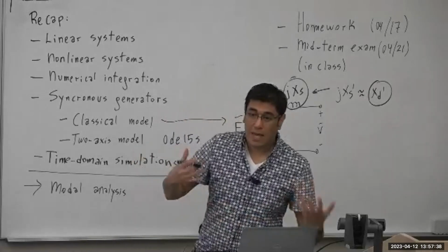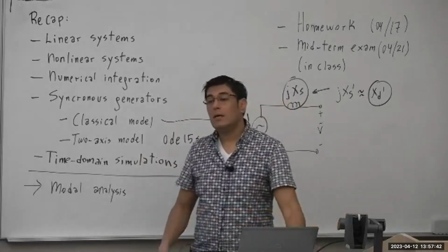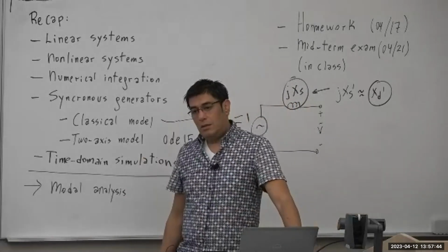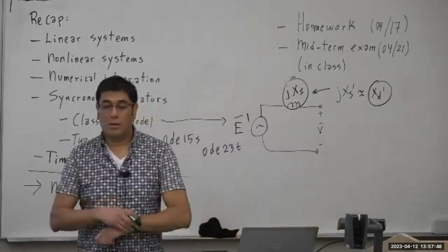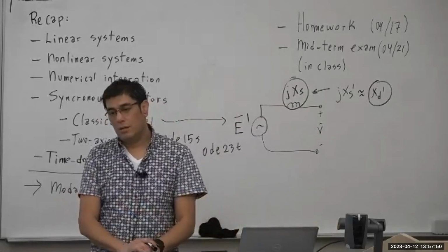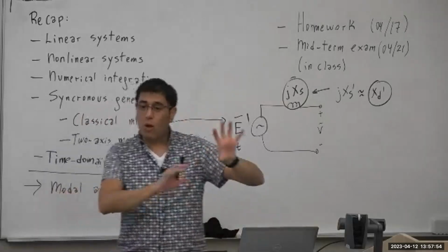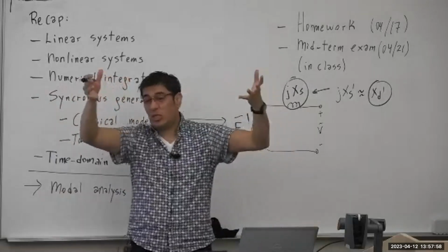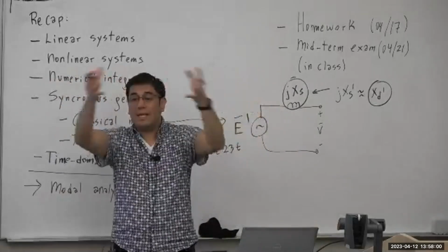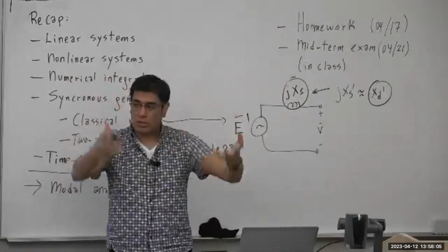we discussed that maybe in the last 1 or 2 weeks. Two machines with a lot of energy going back and forth between the infinite bus and the two machines. Potentially, if they're oscillating in phase. Right. So in the other case it was just one machine oscillating with the infinite bus. With two machines, potentially, if these two machines oscillate together, they will involve more energy in that oscillation.